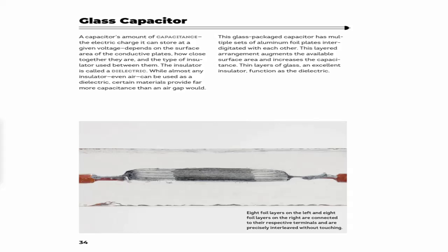The disadvantages are, first, higher cost compared to ceramic or film capacitor. Number second is limited capacitance range. Third is larger size compared to ceramic or film capacitors. Number four is fragility due to glass construction.